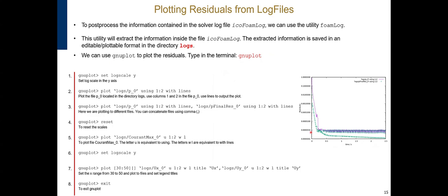To do that, you need to save log files, maybe for your mesh and also for your solver output, which is always printed out on the terminal. If you save it into a log file, then we can use the utility called foamLog to plot the residuals. You could also use PyFoamPlot, a Python utility that could help you do that.